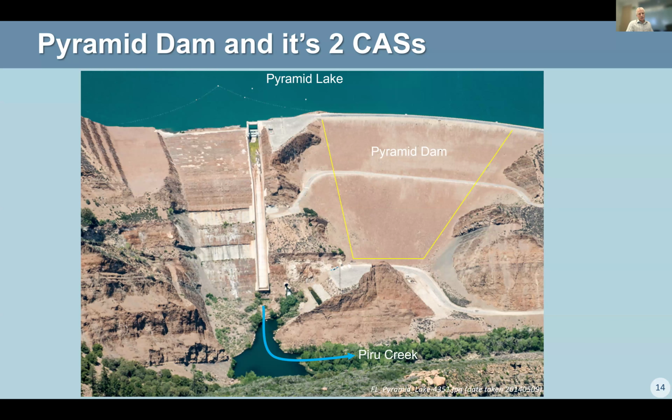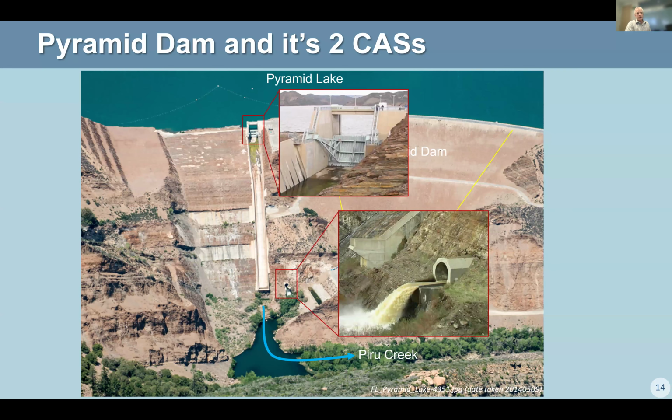But you can also see that there's a gate, a spillway with a gate. So there could be water behind that gate. That gate is higher than 25 feet. It's like 30 something feet. It holds more than 5,000 acre feet of water behind it if it were to fail. So we have to make a map for that. And then there's a tunnel basically that goes under the dam so you can make releases.